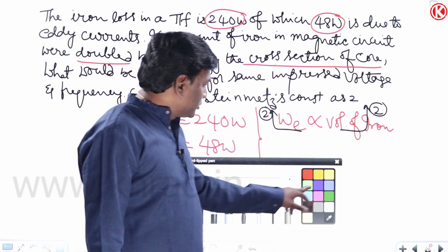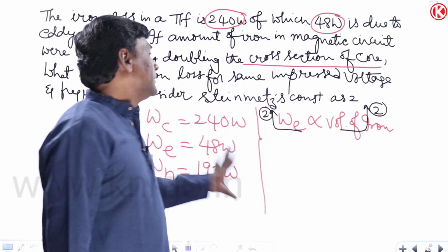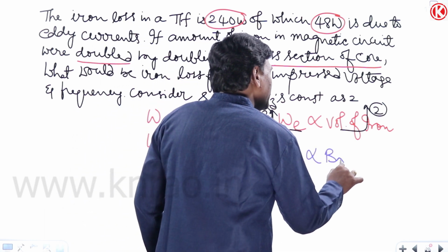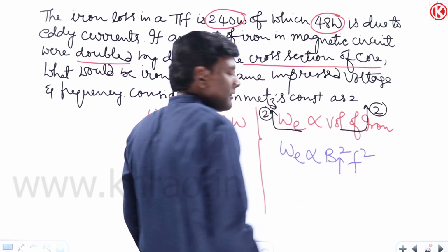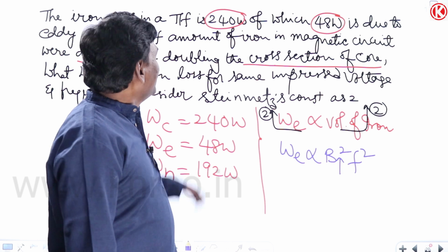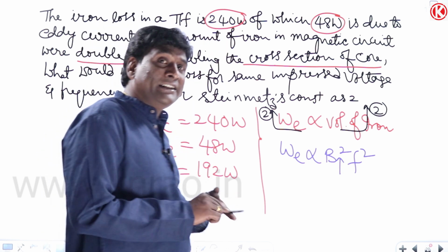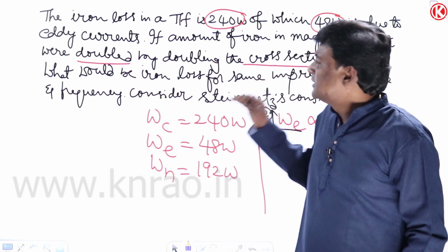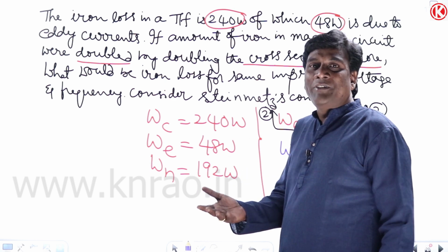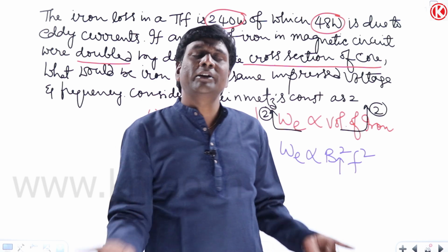And also one more thing is there. You should not say directly. Eddy current loss is also directly proportional to Bmax square f square. Why am I considering this? Though they have varied the design, the operating engineer part is also decided by them, because who will maintain voltage and frequency? The supply voltage and supply frequency for a manufactured machine should be supplied by the operating engineer.